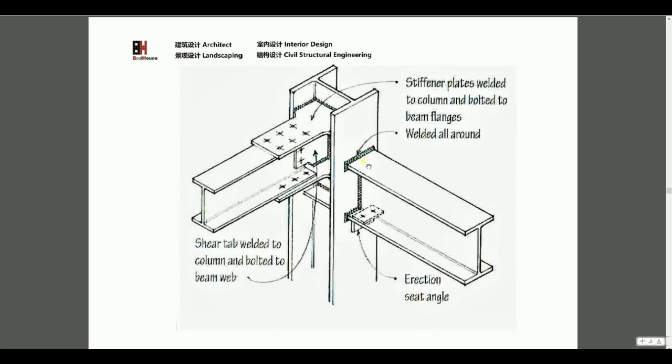So the welding usually is a site welding, but the site welding uses more labor, it is expensive. So for this kind of connection here, we usually weld the plate. The connection plate is welded in the shop, shipped to the site, and bolted the connection at the site.